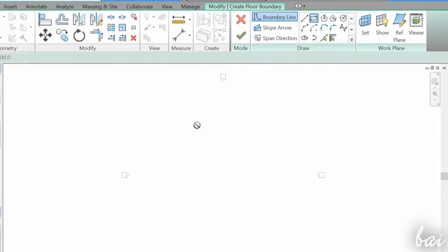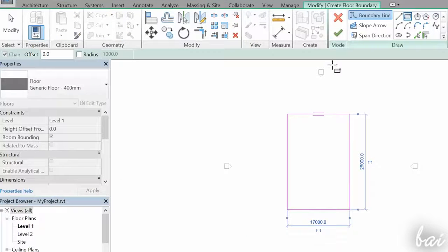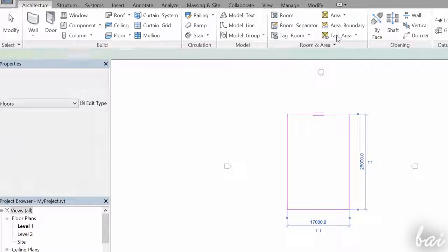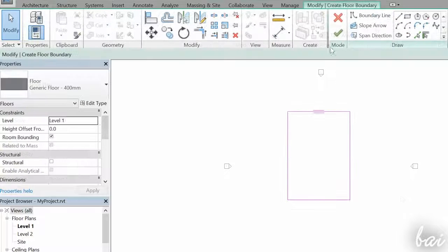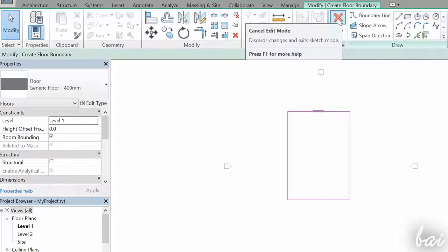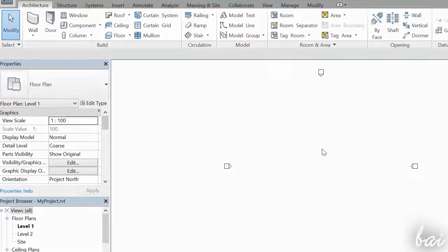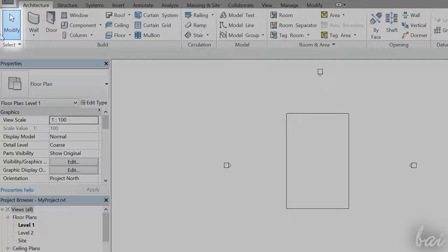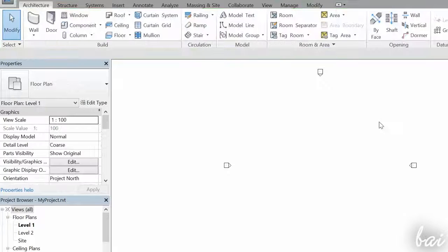As long as a drawing tool is enabled, Revit is in edit mode, which is used to create and edit sketches of objects, shown in pink color. In fact, objects are definitely created when you apply these by clicking on Finish Edit Mode. Objects will also change color and will get volume. If you choose to cancel, you will exit from the edit mode and all sketches will be deleted. You can always delete objects created by selecting them with the Modify tool and using the Delete key.